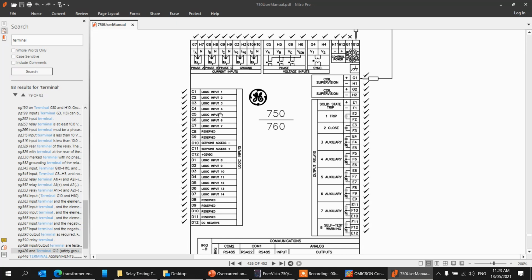It depends on the relay. For example, you see that auxiliary relay that is normally mounted beside the relay. You have to also be very careful on that one. If you have a normally closed contact there and you pull that off without considering where that normally closed contact went, that contact will open. It will trigger a trip upstream.